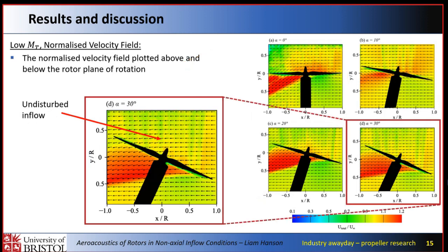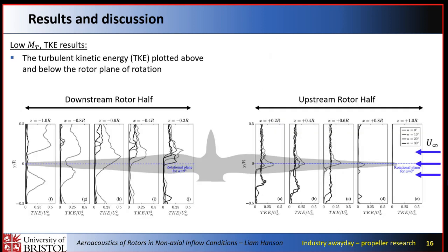What is the comparison of that to forward tilting? Well, you're getting a wake actually in the upstream region, and the inflow is a lot more clean. You're not seeing that sort of translation of the flow from the front to the back end of the blade. And we suspect that's to do with the noise increase that we're seeing. So we know turbulence leads to noise increases, particularly with high harmonic peaks or band increases. So we have to look at the turbulence levels in the flow.